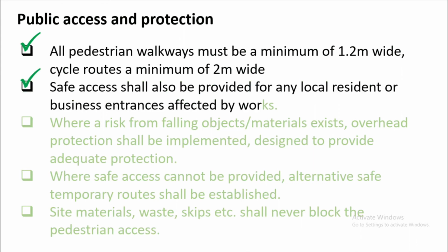Safe access shall also be provided for any local residents or business entrances affected by the work. So if you are doing the excavation in front of a business entrance or access, you need to coordinate with the business owners how you are going to excavate that location without interrupting their business.